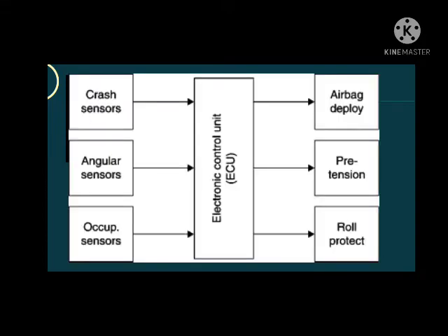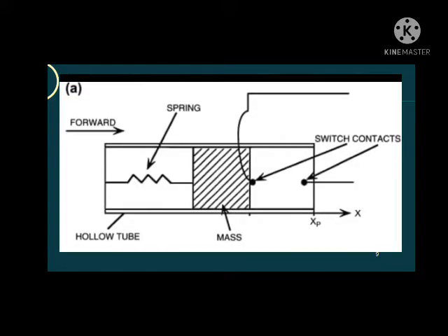The configuration for an airbag system has also evolved from an electromechanical implementation using switches to an electrical system employing sophisticated signal processing. One of the earliest configurations, intended to protect the occupants from longitudinal axis deceleration, employed a pair of acceleration switches, switch 1 and 2, depicted in the figure.